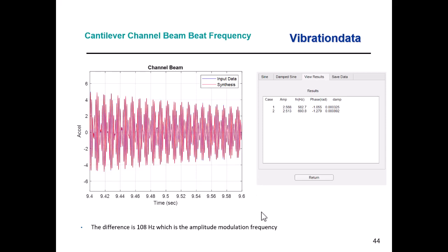What do we design, analyze, and test for in terms of base input and the frequencies thereof? 582.7 hertz, 690.8 hertz, or 108 hertz. So those are three choices, and we could also have some combination thereof. So what do you think the answer is in terms of what frequencies we need to account for? And the answer is a combination thereof, and it's the two frequencies in the results box. So we do not need to design, analyze, and test our RF component to 108 hertz.